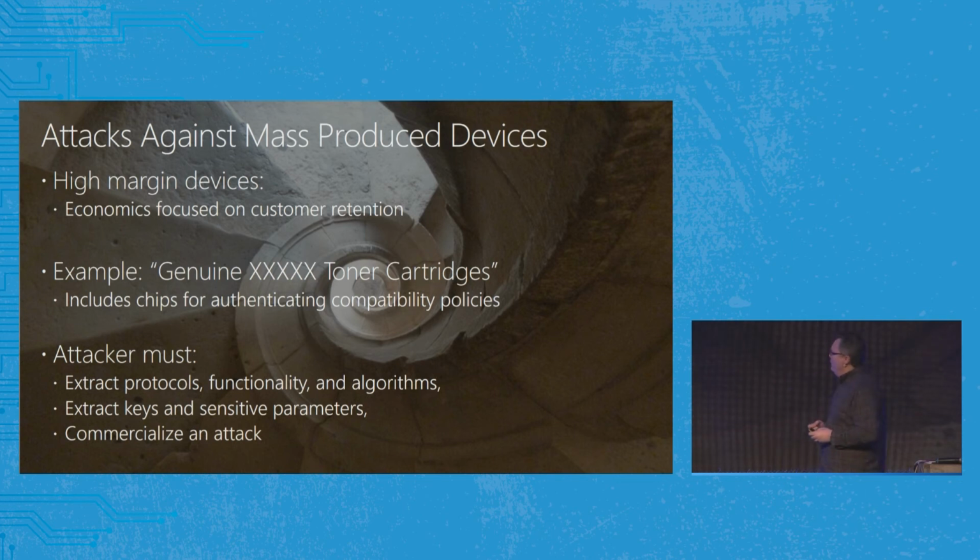The reason this one was an interesting analysis to work through was that these chips are tiny, right? The chips on the printed cartridges, at least in this particular one that I worked on, are about 0.5 millimeter by 3/4 millimeter in size. Imagine those photographs where you saw someone using their finger, holding it above a little sanding disk, trying to move one layer at a time. You try to get something like that flat and remove 7 layers of metal and get the images. Each one of these chips looks like you throw them into a bag and it looks like someone's ground some peppercorns.